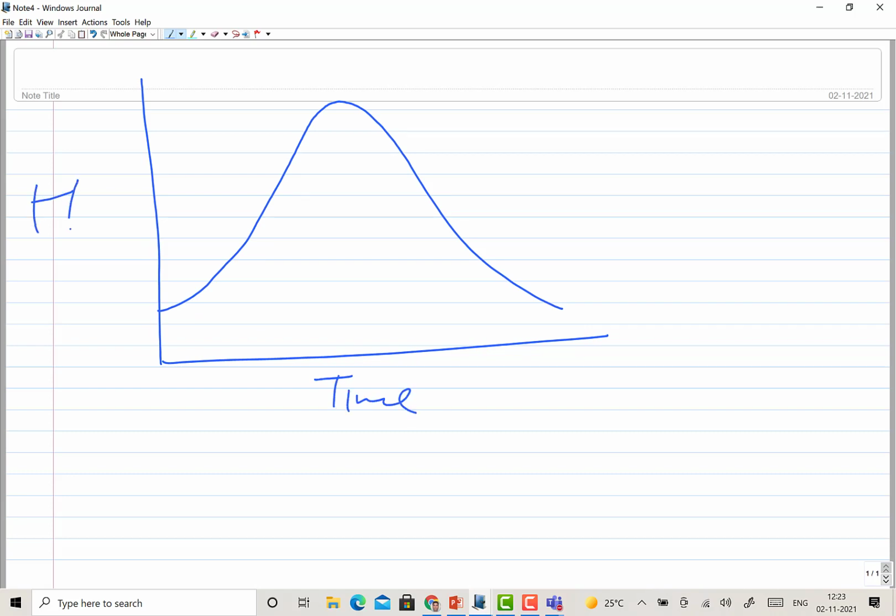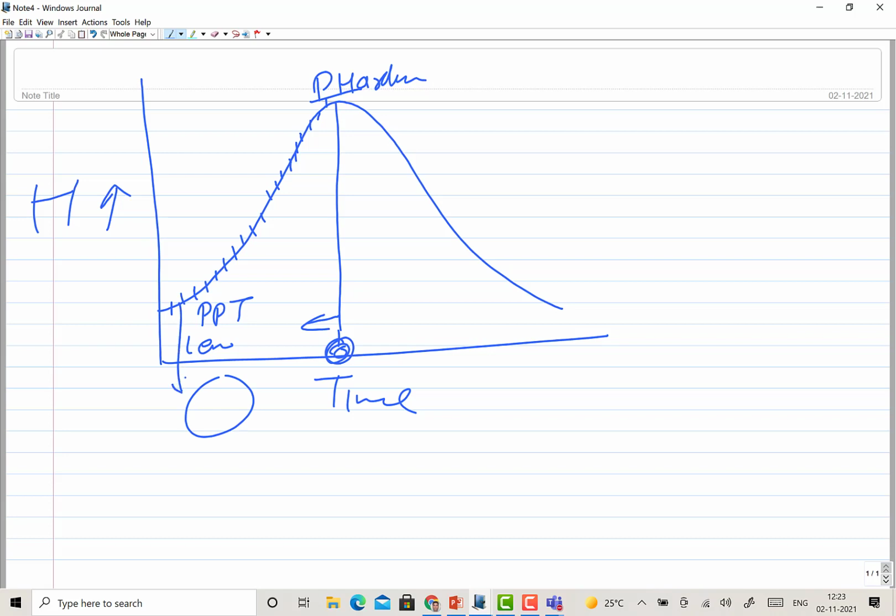Like say the hardness first increases then decreases as a function of time. Here we have the hardness variation. So this is the peak hardness situation. Okay, and this is the time required for achieving the peak hardness. Below that we will find that the precipitates being formed are less. That is why initially there is a continuous increase in the hardness with the increasing precipitation as a function of time. So here you may have had very few precipitates here and there, and after this much time you may have a few more precipitates. Okay, fine precipitates here and there. So this is the difference.